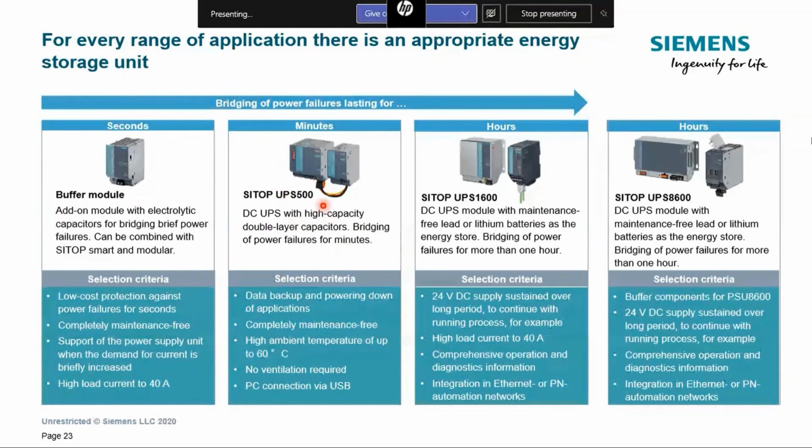This can include taking certain actions in the PLC, or even stopping an HMI application and safe shutdown of a PC, for example, before the power just goes out. And then it goes to an undefined state. Of course, why don't we do that with the batteries? It has the advantage that the capacitors have a higher operating temperature and they are completely maintenance free. So that's why, yeah, they are a good option.